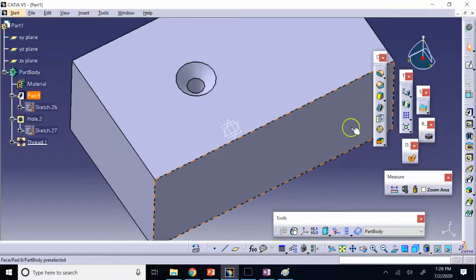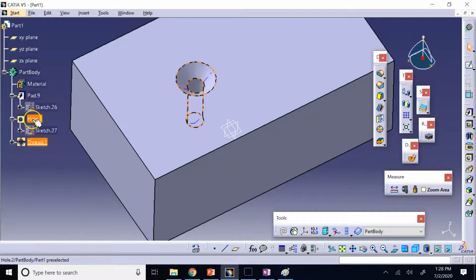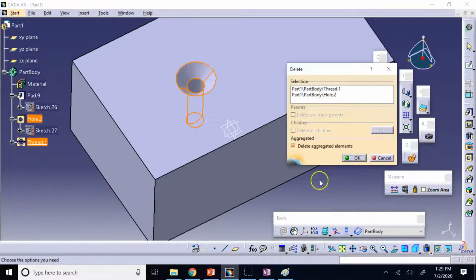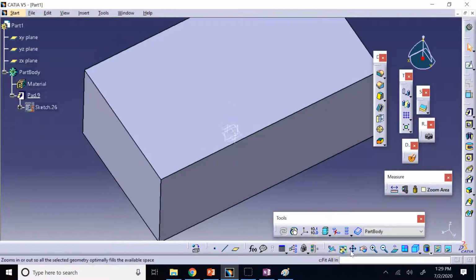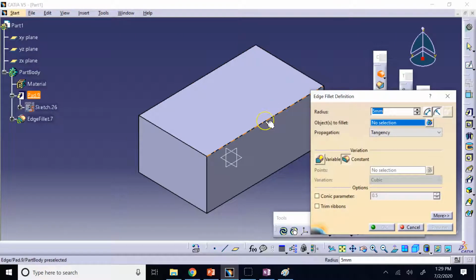Okay, so from this toolbar, I have shown you the draft and tap. Let me show you a few other important things that would be really important and useful for you. So one of them is the fillet command here. So fillet means around an edge. So you can either select an edge or you can select the face. If you select the face, all of the edges of the face will be rounded with this radius or any radius that you provide, or you can only select one edge.